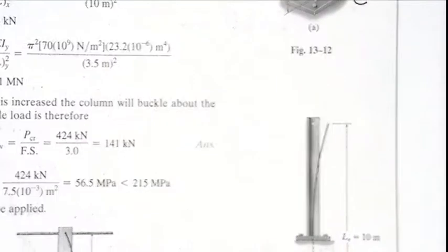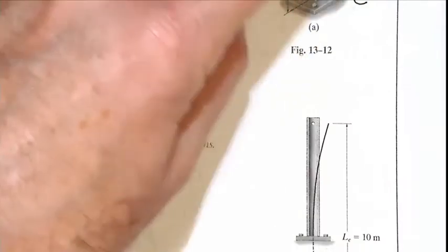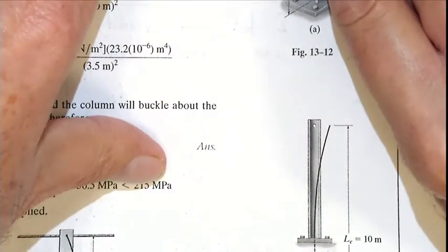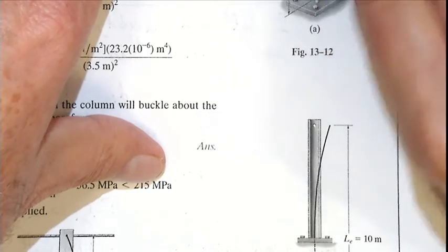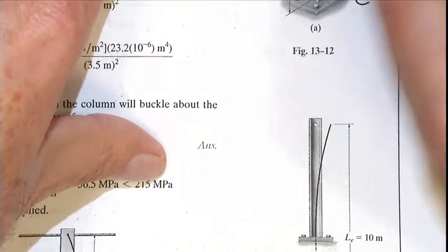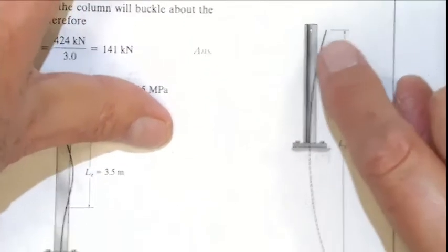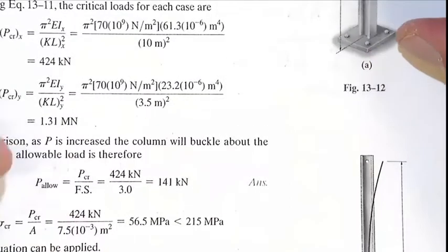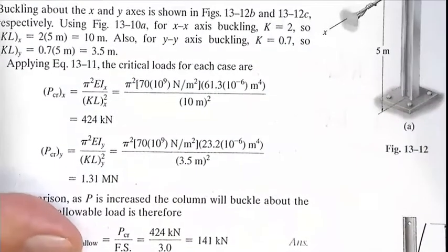So now look, please. Buckling with respect to y-axis, okay? So pay attention. This beam or this bar can move along this. There is this cable. So it can move in this direction along this cable. So that will be the buckling mechanism. So that means that effective length is twice this length. Where is this length?